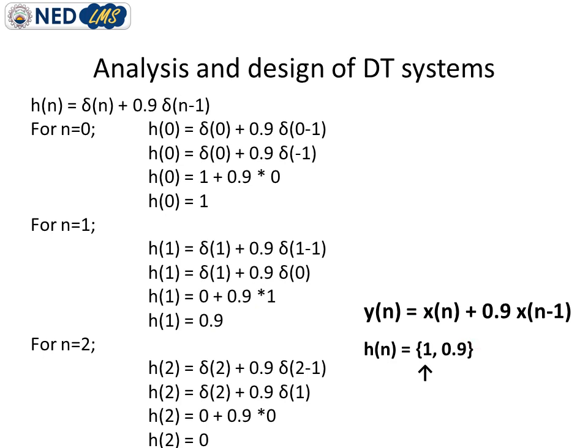And you can see from the impulse response that impulse response exists for certain specific values of n. That is, it exists not for infinite values but for finite values of n. So in this way we can say this is FIR system, which is finite impulse response system, as its impulse response is calculated to be finite.